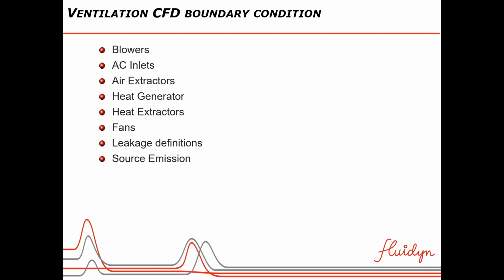Whenever we come to ventilation, the input conditions for the problem definition are very important. Normally we give boundary conditions on the boundaries. Apart from boundaries, we can also provide special element source information in the domain, as a point, as a group of cells, or as a phase. So we have many options. From the user's point of view, there is no need to model that as a boundary. Even as a point we can introduce whatever we require.